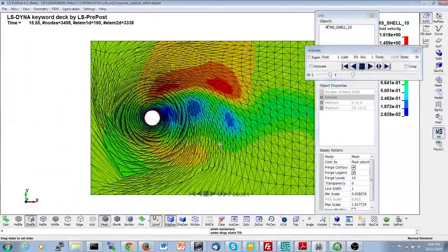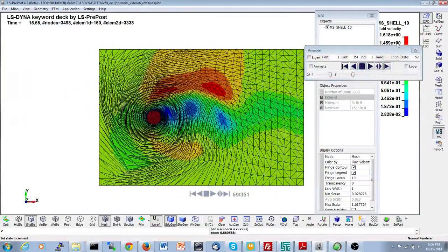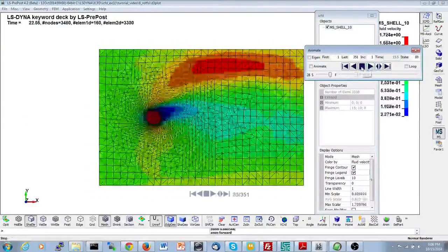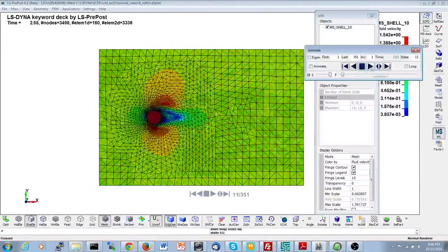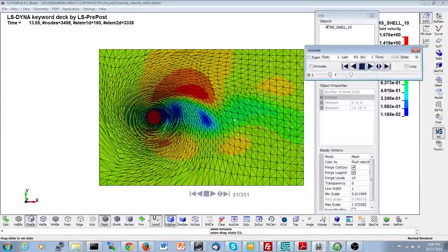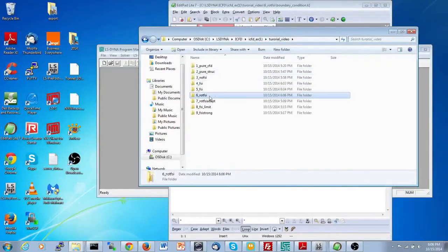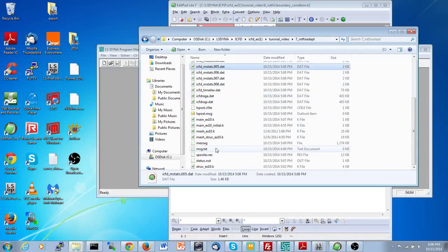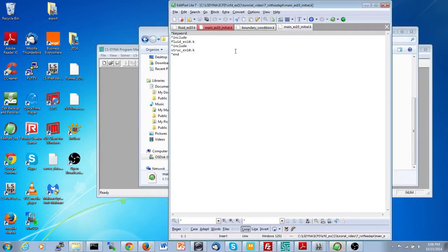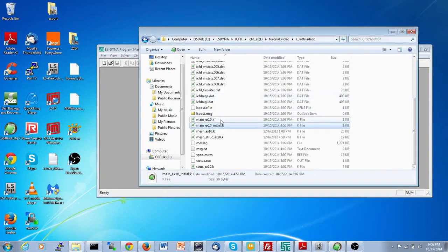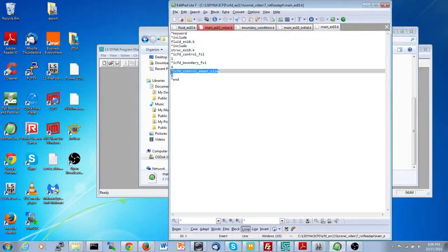the solver to remesh a little bit more often than only when an element gets distorted. We'd like the solver to remesh. Well, if the mesh gets too distorted, please remesh. So there's a keyword. The keyword for that is called ICFD control adapt. Let me open here the right file. There you go. So here it's called ICFD control adapt size.